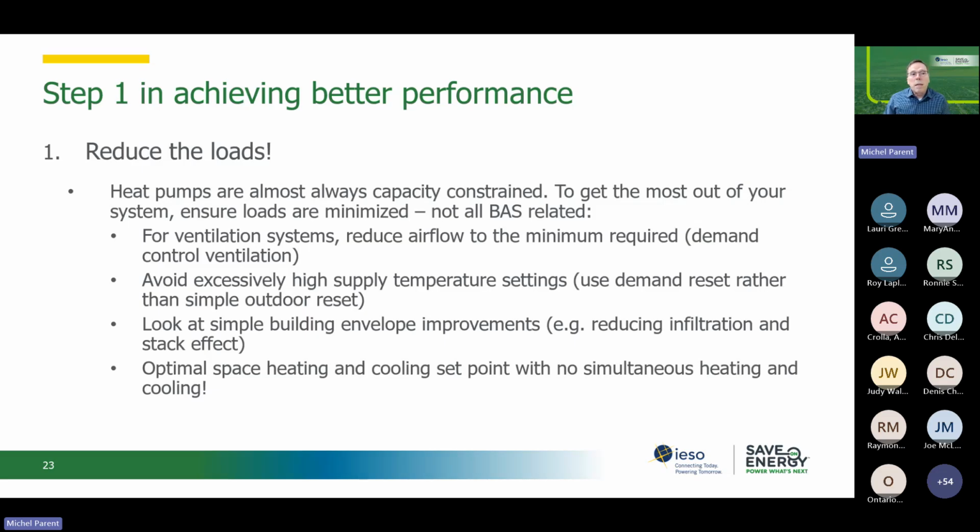The heat pump system is usually capacity constrained, so you want to make sure that this load is as low as possible. So before you start integrating and programming the control sequence, review all the other control sequences. Make sure that you are optimized. You could do the recommissioning, you could do a BAS optimization prior to jumping into integrating the BAS.